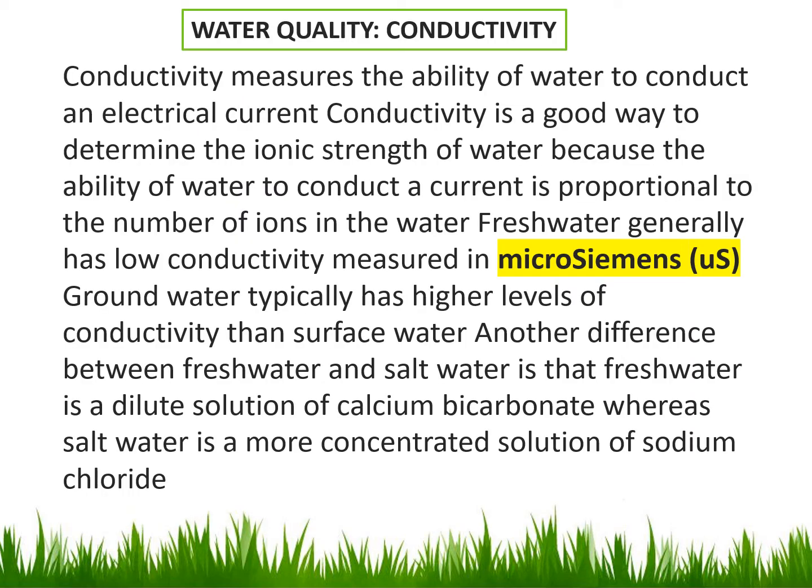Now we will be talking about water quality in terms of conductivity. And what is conductivity? It is the presence of ions, because electrical conductivity can only take place in the presence of ions, and it indicates how many ions are present in our sample. A higher level of ions means a higher tendency to carry TDS. So it gives us a direct relationship. EC is directly linked with the TDS level, and it is measured in microsiemens.